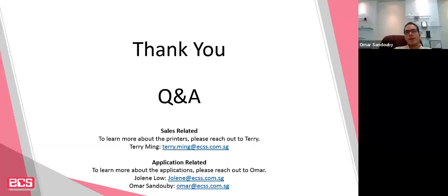Okay, so for accuracy, there's one linear equation that we have for our material jetting technology. If I'm not mistaken, it's about 20 microns per inch of part. So if you're talking about a part which is 1 inch, 25.4 mm, you will have an accuracy of about 20 microns or so. The more you increase the length, the accuracy would correspondingly have to be adjusted. So if you're talking about 50 mm, then it's about maybe 40 microns, which is 0.04 or 0.05 mm.